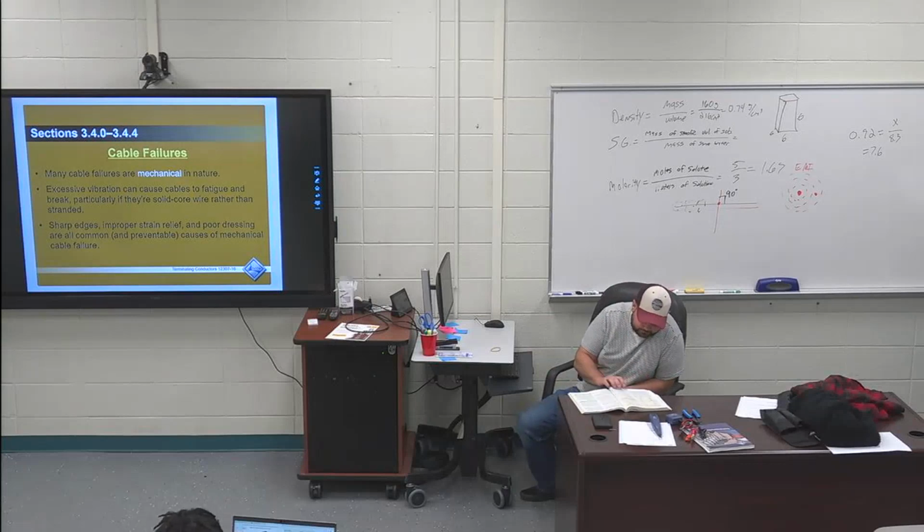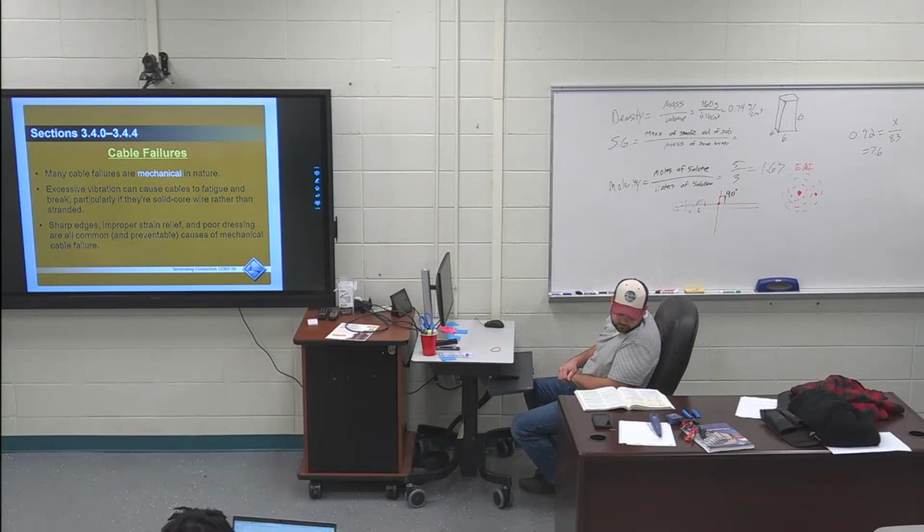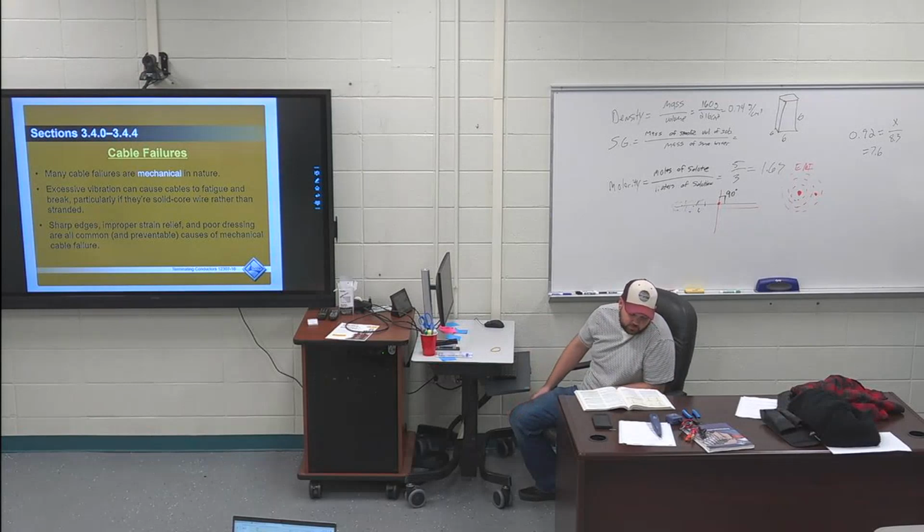Page 48. The paragraph that's right above 331. The last, is that all one sentence? The last sentence is highlighted. It's more than half the paragraph. If the required equipment is not immediately available, the DC loop resistance of conductors or coax cable can be measured using a multimeter to set up, measure resistance, and cable length or distance to a short can be approximated as described in the following section.